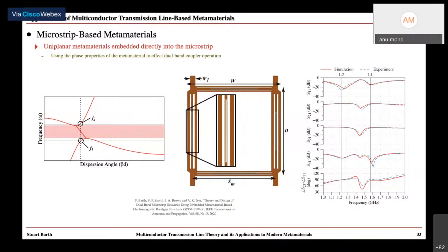Well, that's a good question. I myself have only worked with it to X band, but of course, all of this theoretical analysis and everything I've done hinges on the core concepts of transmission line theory, which really, at its core, deal with the propagation of voltages and currents. So to answer your question, I would pose another question, which is, in what frequency range can we define voltages and currents? And of course, as you know, this hinges on things like the TEM approximation, where we assume that the fields of the modes are predominantly existent in the transverse plane, transverse to the direction of propagation.